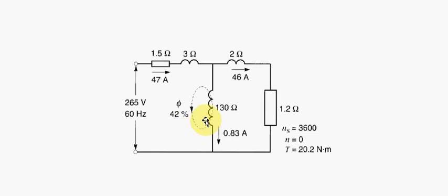Here's another condition where this current goes a little bit wayward as well. Right? Here we've actually locked the rotor, and if we lock the rotor, then what's happening here is you can see that the majority of the current actually flows down the rotor circuit and not down here. As you can see, it's 47 amps and there's 46 amps, and this is now the equivalent to the short circuit test in the transformer.